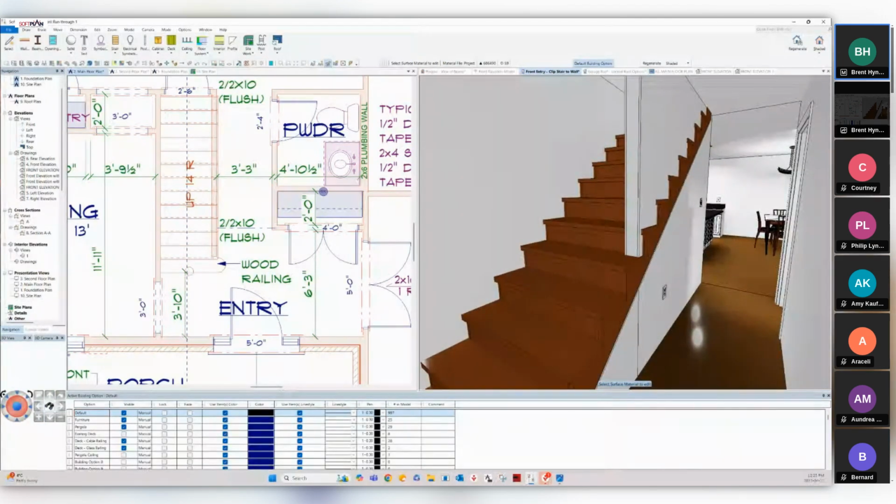All right. With the clip stair to wall option, this will address the instance where you have a stair that goes up at say 42, 45 inches wide and it intersects into the end of a wall that's been cut back or pushed back, and then you need to reduce the width of the stair. In previous versions, you would have to draw that as two stair components and connect them together into one stair. We are just basically doing the same thing for you, but we're automating it for you. So to use this tool, what we want to do is remain at that width going up to where that wall is, and then have it reduce its width at that point.